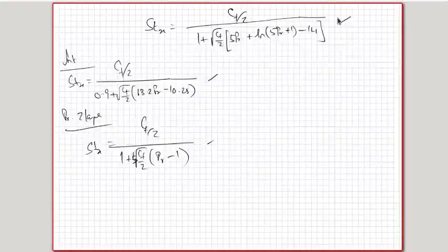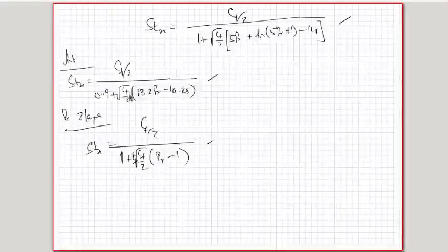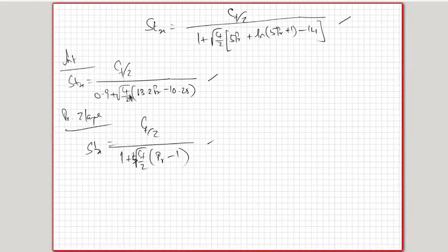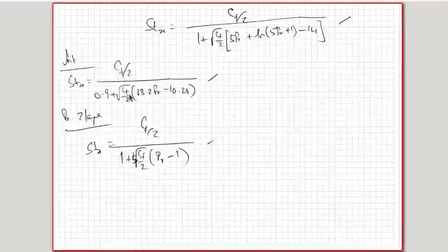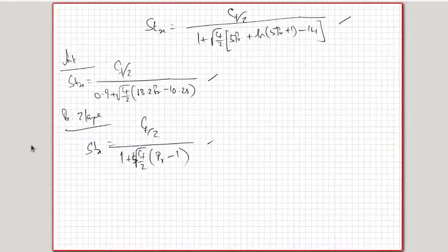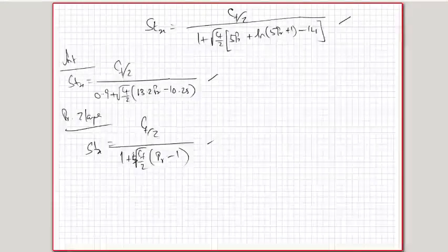So they're all quite similar to each other, and you find that you are able to get these expressions of the Prandtl and Karman much more simply than the integral method. Integral method involved a little bit more complexity, but even this is a simplified method. But complete theoretical solution to get the turbulent boundary layer profile requires direct numerical simulation, so we have not done that, but mostly the data from experiments is used to verify this.